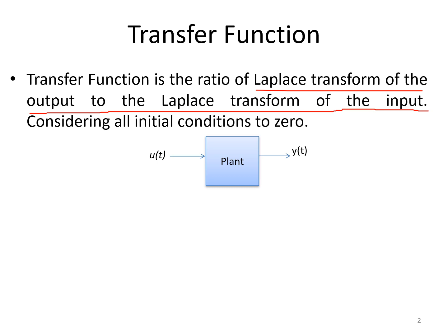In a simple way, a transfer function is nothing but the transform of the output to the transform of the input. It could be the Laplace transform, the Z transform, or the Fourier transform. Whatever transform you want to consider, you can consider. But for the analysis of control systems, we are going to consider the Laplace transform to identify the transfer function for a particular system.